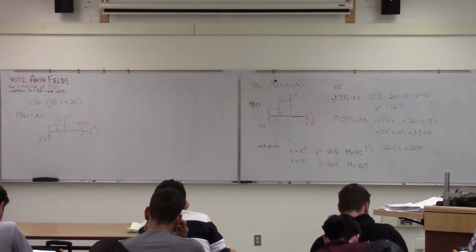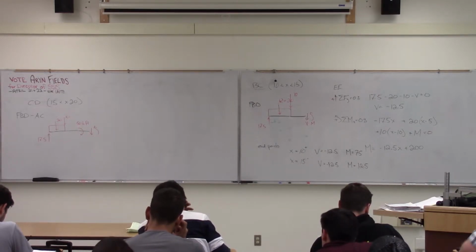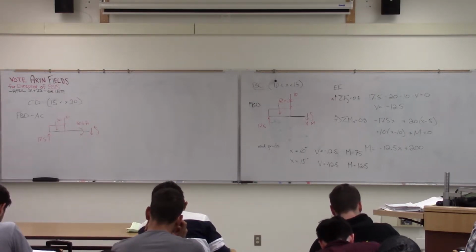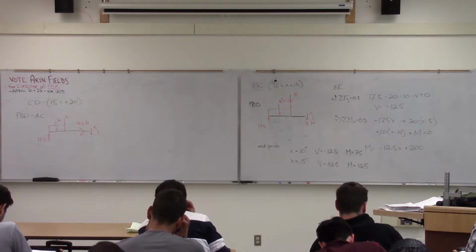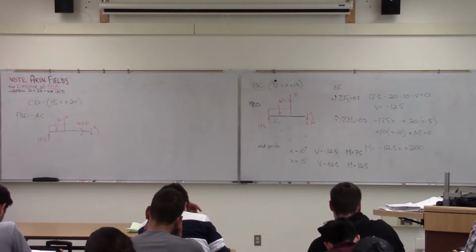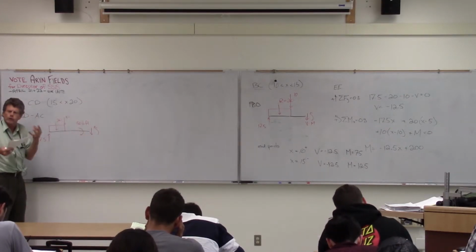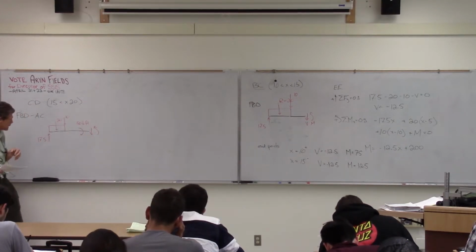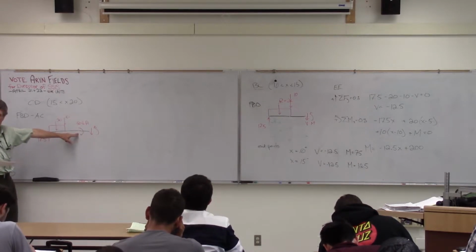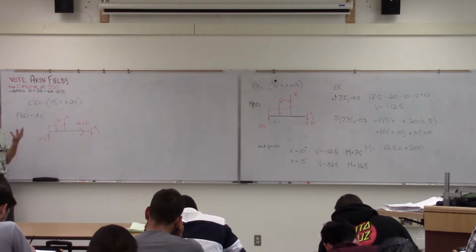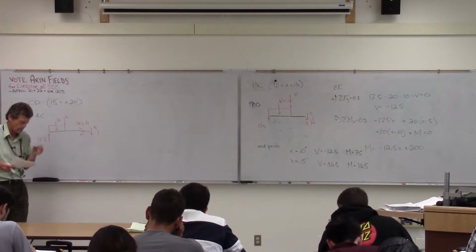This is going to be like a method of joints and trusses and that sort of thing. In terms of this equilibrium approach, we're just going to be doing equilibrium body after equilibrium body. The key thing is what's happening is as we go from section to section there, we're including more forces in that free body diagram. So what we've done now is we've gone now past point C there, and all of a sudden this 50 kip twist shows up.